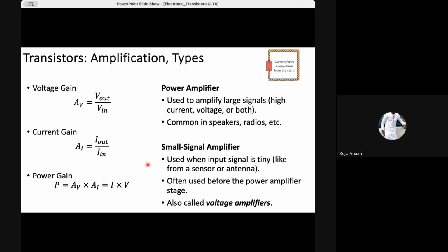Well, sir, I think it cannot be considered as an amplifier. Can you justify it? My reason is that even though they are both raising voltages, they work differently. The transformer doesn't need an external source of power, unlike what you already stated concerning the transistor, that two important things have to be available, which are the external source of power and the signal. But the transformer doesn't need any external source of power.